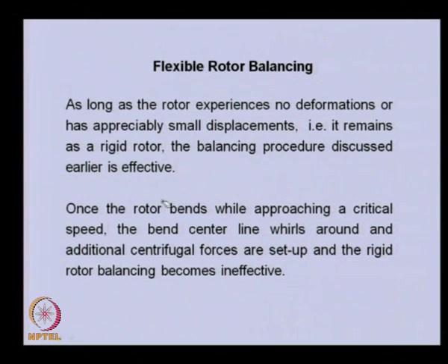But when the rotor speed increases and the rotor bends while approaching a critical speed, the bent center line whirls about the bearing axis, and additional centrifugal forces are set up, and the rigid rotor balancing becomes ineffective.